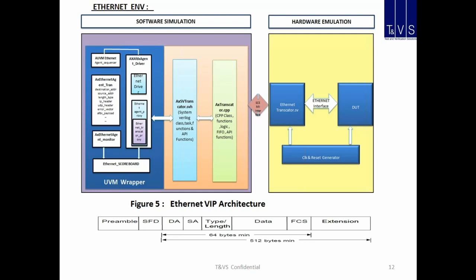So for example, if it was an Ethernet SOC, you could be driving Ethernet packets into the SOC through the emulator using the software simulation. Design size is large, right? Then you can't really put the whole thing in the emulator and also have a UVM test bench, which you can. The emulator can, depends on your emulation provider. But sometimes you have to, depends on the capacity of the emulator.